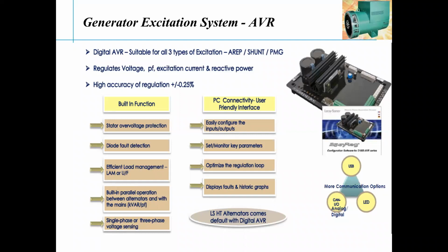So in the built-in functions, it has protection of stator voltage. It can do diode fault detection, efficient load management, the under-frequency roll-off or load management system, and built-in parallel operation between the generators or the grid. Both can be done with power factor or kVAR sharing, with single-phase or three-phase sensing, which is a customer demand. In India, earlier it was predominantly two-phase sensing. We put in one more module to monitor three-phase, but again, it brings a three-phase sensing circuit, easily configurable and customer-friendly. Anybody can do this, play with it like how you are playing with a mobile.